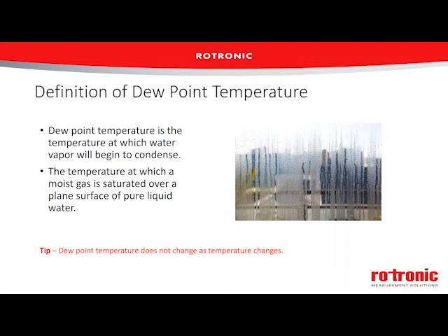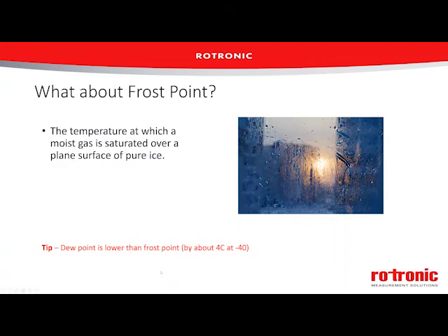So as the temperature changes, the dew point temperature does not change. It remains constant. What does change, though, is if pressure changes in a system, then the dew point temperature will change. So some people can get that confused at times, but dew point temperature is not temperature dependent.